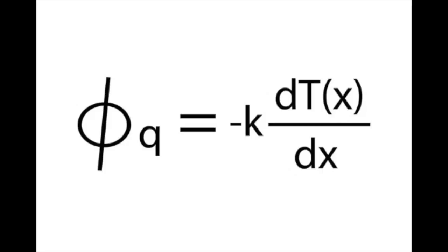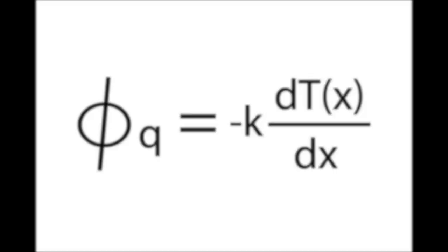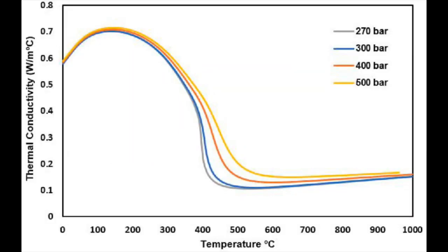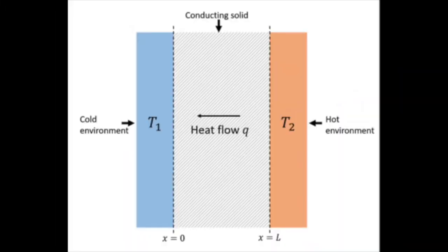Heat flux at the solid-liquid interface is continuous, so we can equate the heat flux occurring through the solid as well as the liquid at the interface, and we will use this equation to experimentally determine the thermal conductivity of the solid material. We found the thermal conductivity of our liquid, which is water, through a Google search, and in our experiment, we're going to be determining the conductivity values of different materials like aluminum foil, styrofoam, stainless steel, and glass.